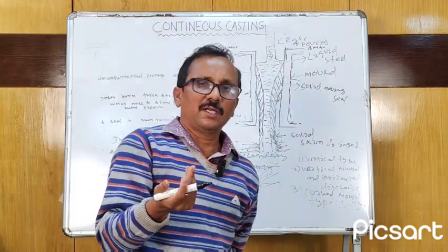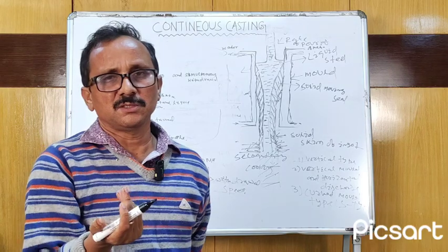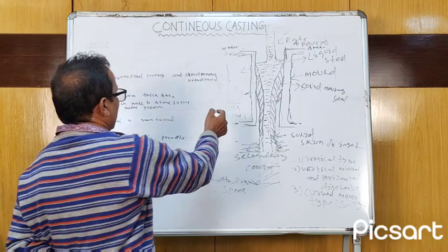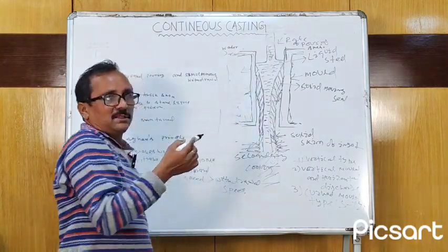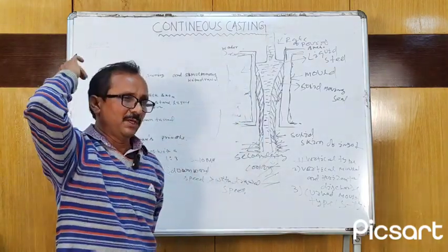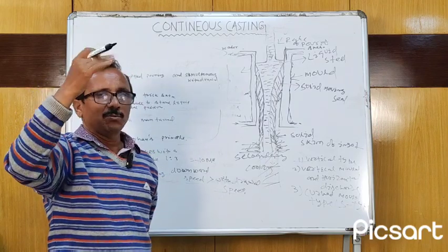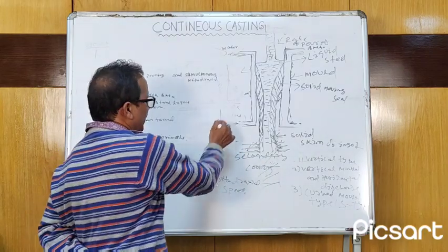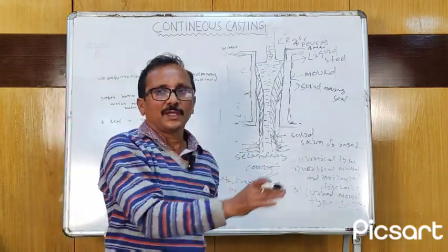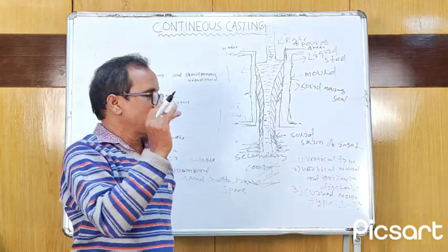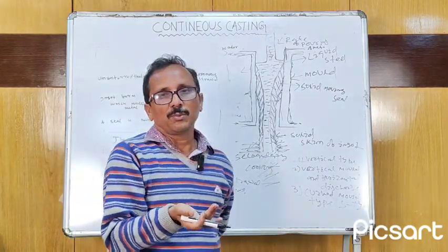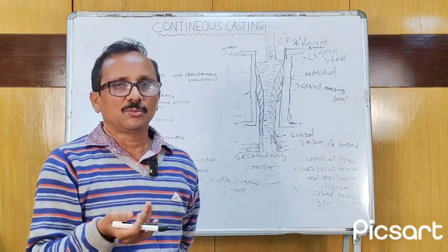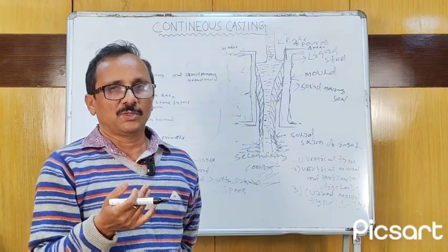In this way there are different types of continuous casting machines, and we get products in different ways. But in the vertical type, the shop floor needs more height, around third or fourth floor. So to maintain a low height, we go to the S type, and we can take a longer distance with small height. So we can cast different products. Nowadays all are cast in continuous casting machines, which are more advanced and give a good process.